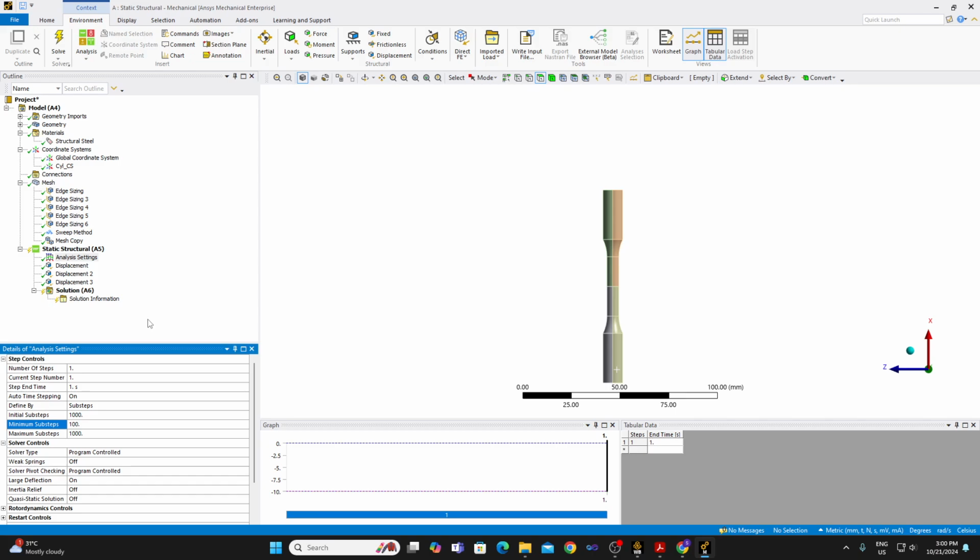happens, the material stiffness abruptly changes, and I do put emphasis on the word abruptly because it does. When the stiffness abruptly changes, the solver has to take multiple steps to resolve that. And you can imagine the yielding happens at the end of the elastic limit, so you need more than one step to do that. So it is better to have more than one substep within the elastic limit. That's why I'm going with 1000 initial substeps.